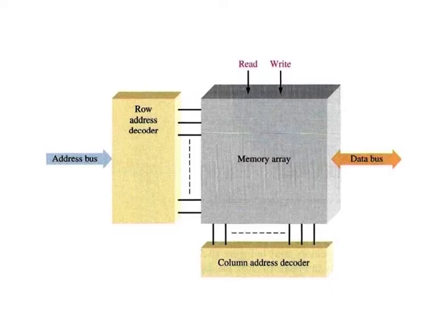The number of lines in the address bus depends on the capacity of the memory. For example, a 15-bit address code can select 2 to the power 15 locations in the memory. A 16-bit address code can select 2 to the power 16 locations in the memory, and so on. In personal computers, a 32-bit address bus can select 2 to the power 32 locations, expressed as 4G.